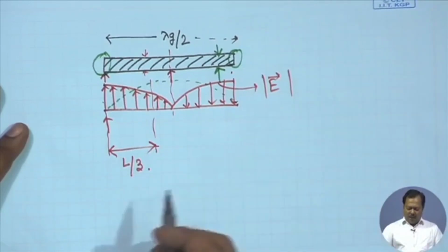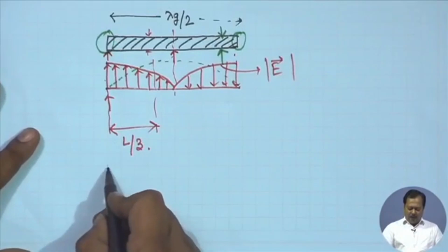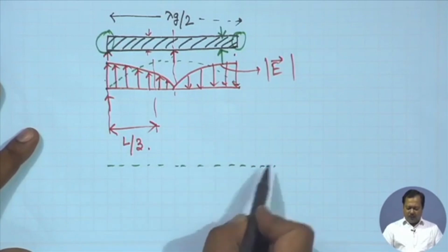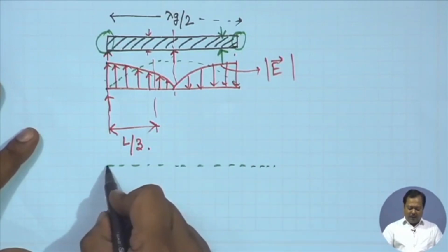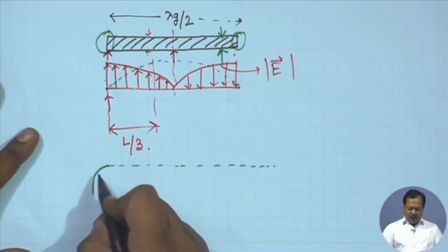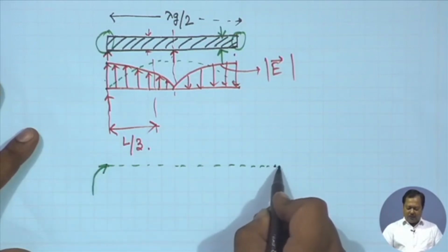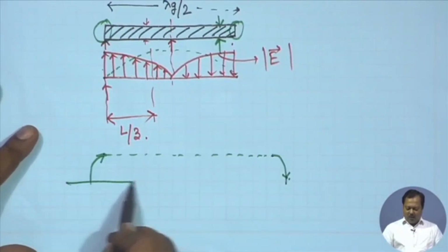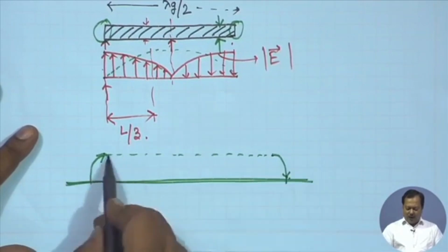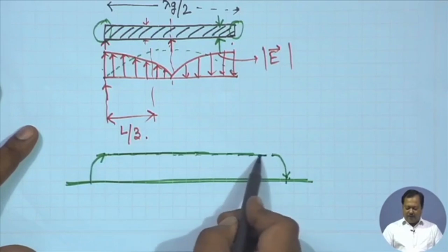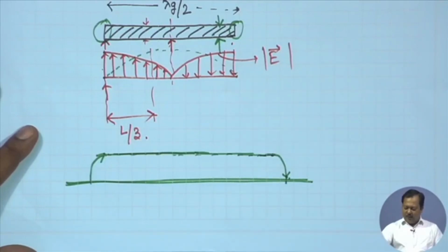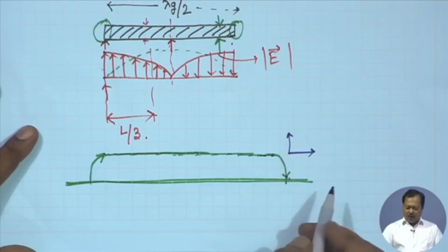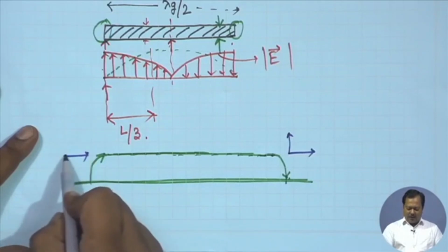Now, how do we have radiation from the fringing field? Obviously, for that, the electric field and magnetic field have to be in the same phase. So, let us say these are the fringing field components. I am drawing the side view. At the bottom we have the ground plane, and this is the top strip. Now, I can represent the fringing field along two orthogonal axes.